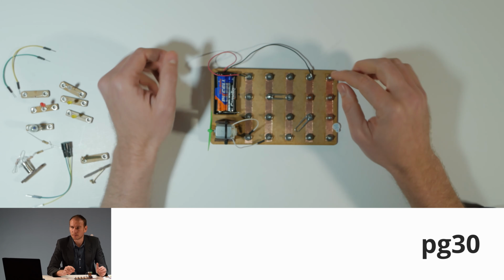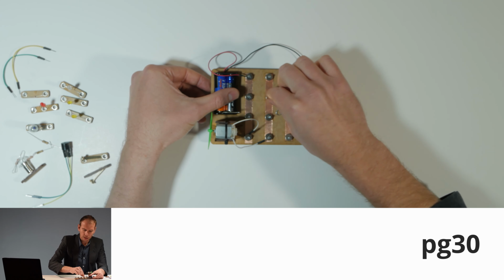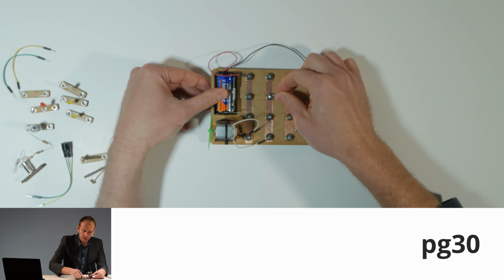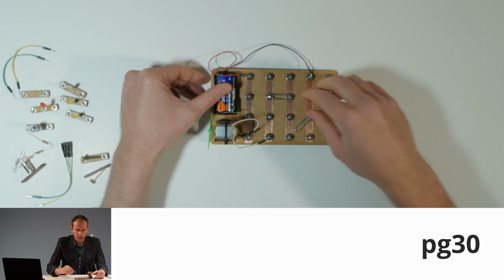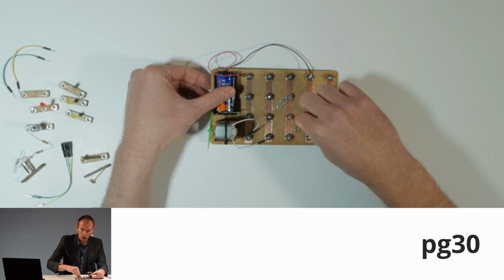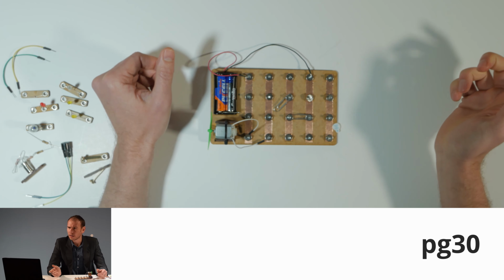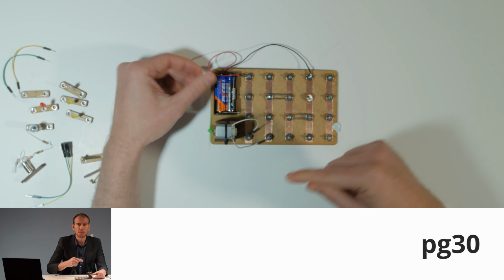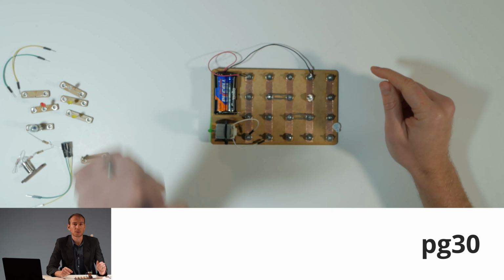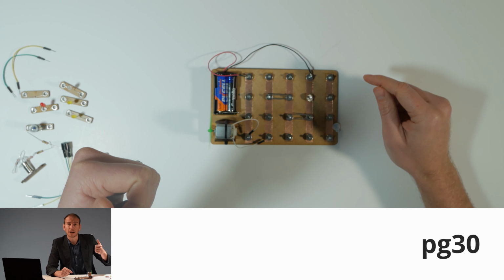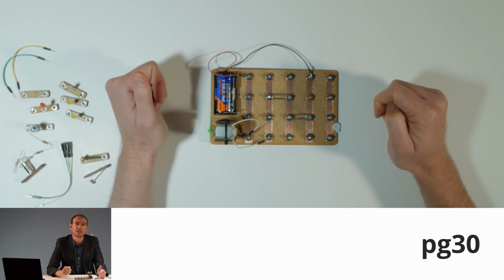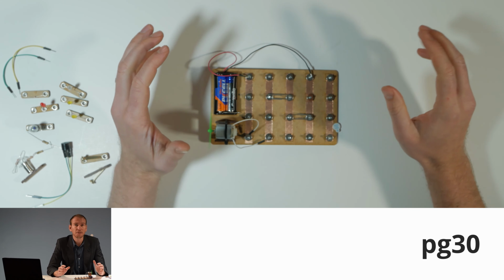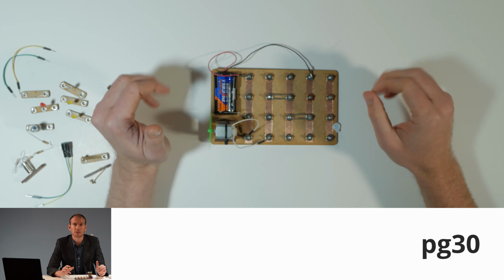That table says that if both switches are off, both switches are 0, the motor will be off. If switch 1 is on, the motor will still be off. If switch 1 is off and switch 2 is on, the motor will still be off. But if both switches are on, the motor will be on. And this is exactly what we want. We want to switch the grinder on at the wall and physically on the grinder itself for protection, so that it doesn't just randomly come on. So go ahead, play around with this circuit, have fun, see if you can create some of your own circuits with this one.